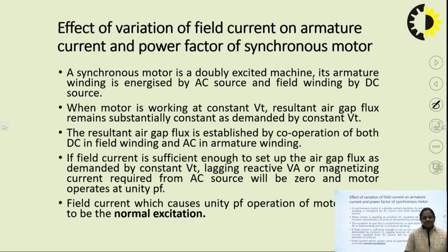Now, let us discuss another important topic in the three-phase synchronous motor. It is the V-curves and inverted V-curves, right? V-curves and inverted V-curves are actually the result of a particular behavior of a three-phase synchronous motor which is obtained when we vary the excitation given to the synchronous motor.